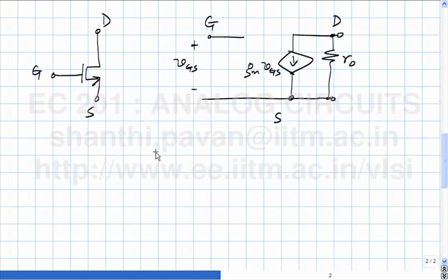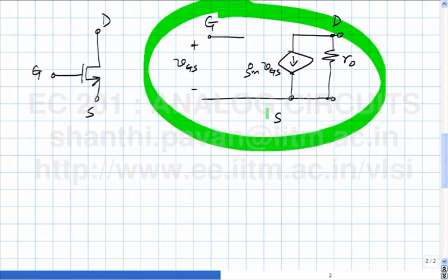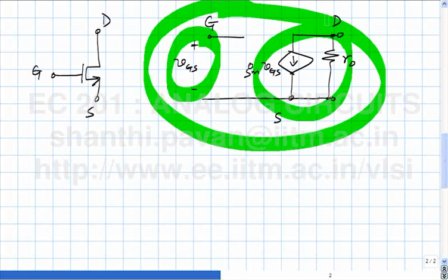If things become smaller, presumably charge carriers have to move by shorter distances, which presumably means that devices can be expected to get faster, and this equivalent circuit would predict that the MOSFET would respond with infinite speed. So if an incremental VGS was applied, this equivalent circuit would mistakenly indicate that the incremental output current is GM VGS, and that happens right away.